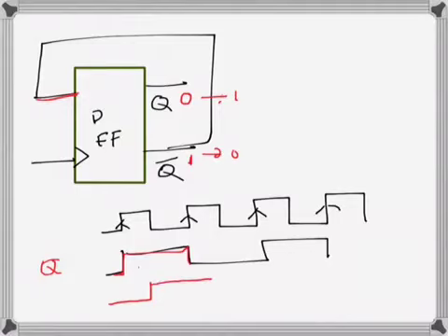So this much is the propagation delay, T P low to high in this case, and again for the second one it will be high to low. So this much will be TPHL, depending on which one. So this is the propagation delay, and then before the next clock comes, we also need to compensate for the T setup time, which has to be there.